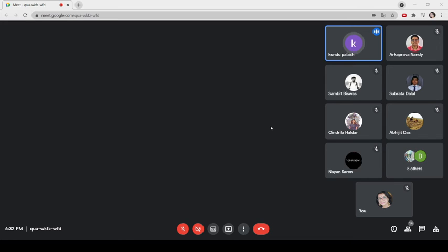In 8051 application, we have learned how the time delay generation can be programmed using a software counter. That means using instructions with a control loop. But here it is not required because once the timer is programmed and configured, the programmer only has to calculate the appropriate count value for getting the given time delay in seconds.